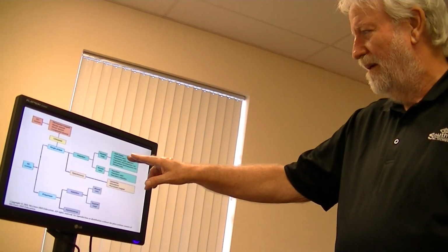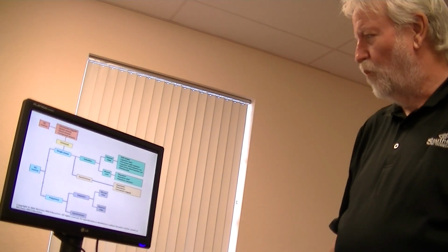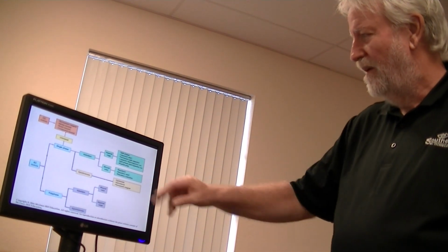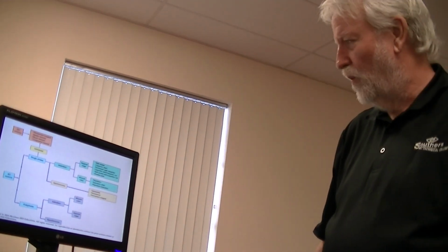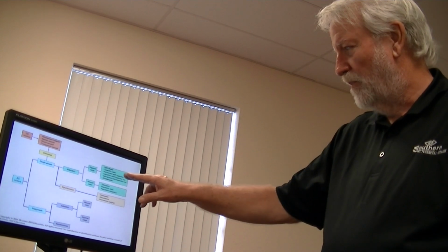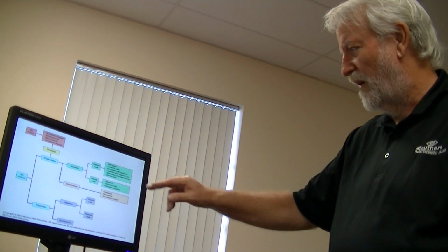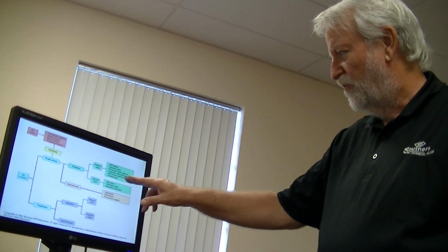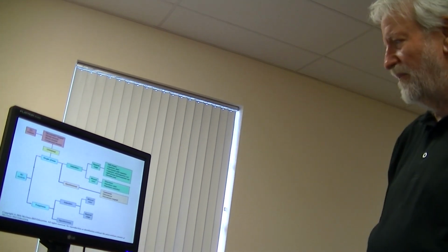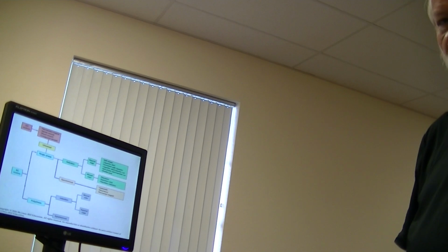But getting it there is another thing. So split phase is one of the processes they use there. A capacitor start is another one. And then you've got permanent split capacitors. You've got capacitor start and capacitor run. You've got split phase start, capacitor run. You've got shaded poles. There's all different kinds.